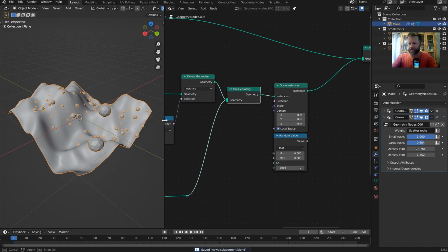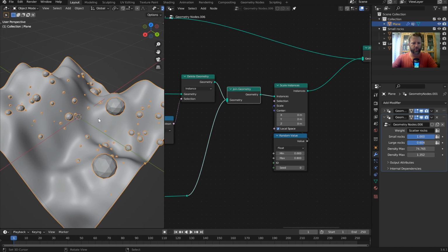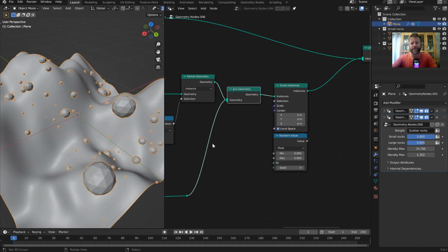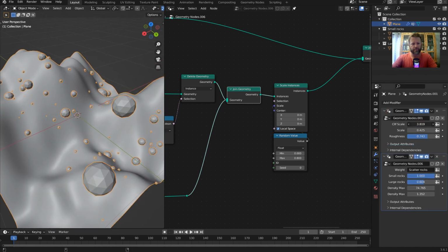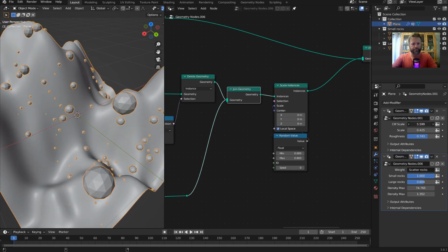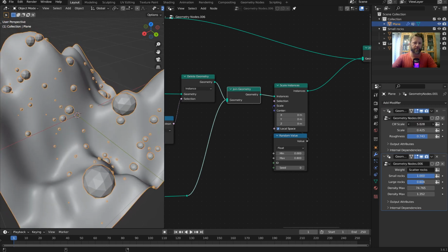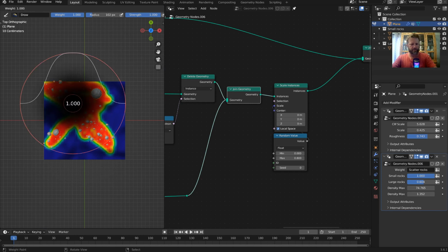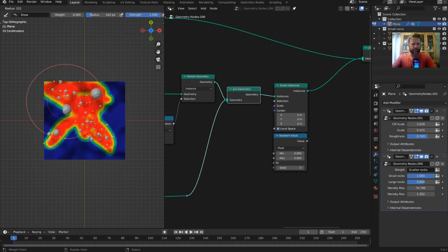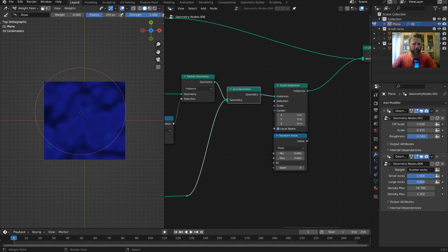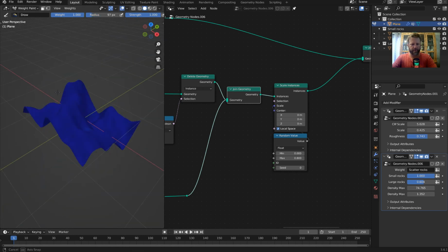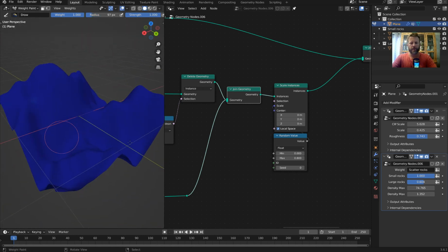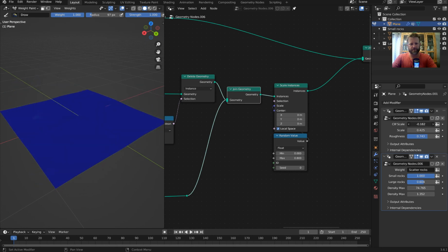And this is just about all I'm going to do on this one, because this tutorial is going a little bit longer, but this will give you a good idea what you can do. You've got the setup here now. You can make the cliffs. You can procedurally do whatever you want with it. You can come in here with the weight paint, and I'm just going to hit Control F and go to 0, and then tap F, and I can wipe all of this out and go back to 0. I can bring the weight up, tap F. I can put this anywhere I want.